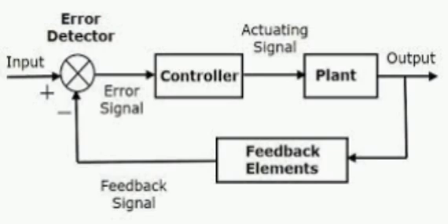Time response of a first order control system. Transfer function: C(s) by R(s) equals 1 by s tau plus 1. Response to the unit impulse function: the time response expression is c(t) equals 1 by T e to the power minus t by T u(t). Response to the unit step function: C(s) equals 1 by s into (s tau plus 1). Time response expression: c(t) equals the inverse Laplace of C(s), equal to 1 minus e to the power minus t by tau, u(t).